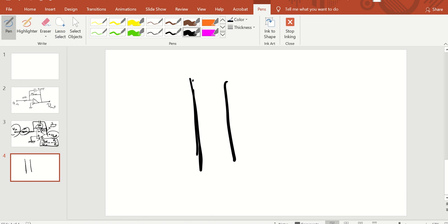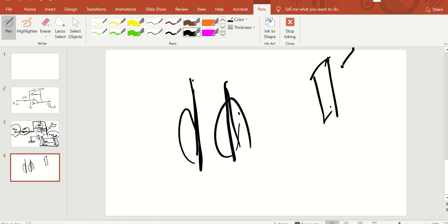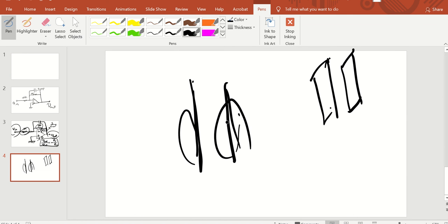Because even in breadboards, what will happen is called capacitive coupling, because you have charge, and because of that, these two wires will act like capacitors, right? And the coupling will happen between these two wires, and that will eventually create noise, and outputs that are not clean or deviate from your original signal. So that is one of the things you have to be careful about.